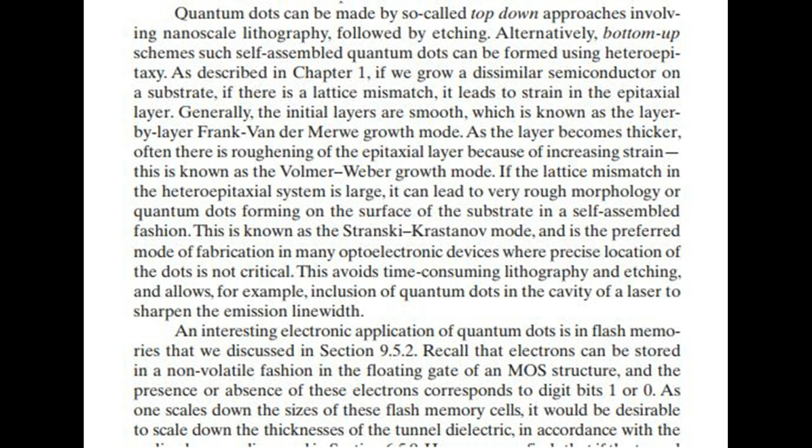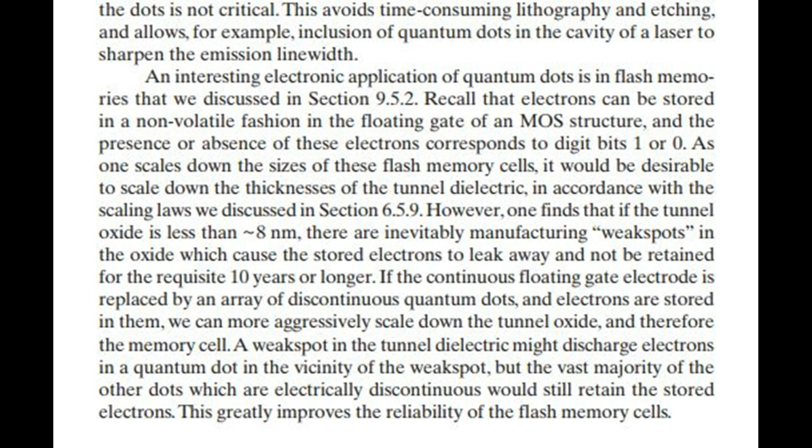If the lattice mismatch in the heteroepitaxial system is large, it can lead to very rough morphology or quantum dots forming on the surface of the substrate in a self-assembled fashion. This is known as the Stranski-Krastanov mode, and is the preferred mode of fabrication in many optoelectronic devices where precise location of the dots is not critical. This avoids time-consuming lithography and etching, and allows, for example, inclusion of quantum dots in the cavity of a laser to sharpen the emission line width.